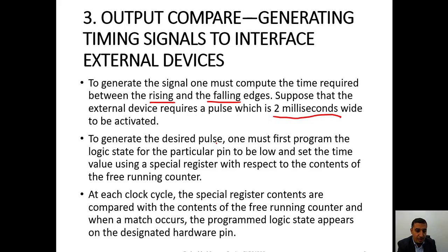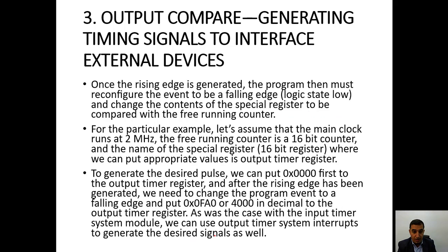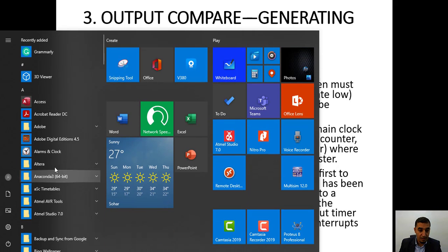Now, to generate the desired pulse, one must first program the logic state of the particular pin to be low and set the time value using a specific register with respect to the contents of the free running counter. At the clock cycle, the special register contents are compared with the contents of the free running counter, and when the counter matches, the programmed logic state appears on the designated hardware pin. Basically, what we try to do here is...